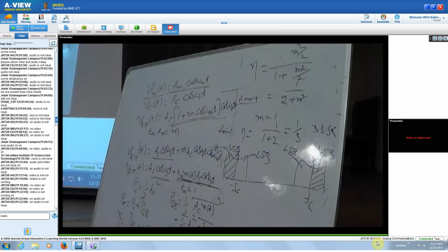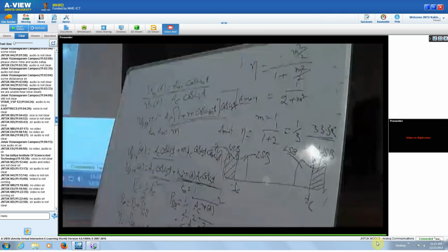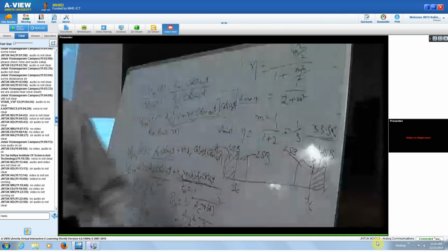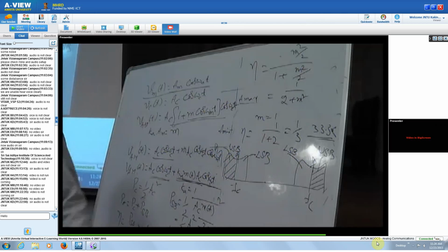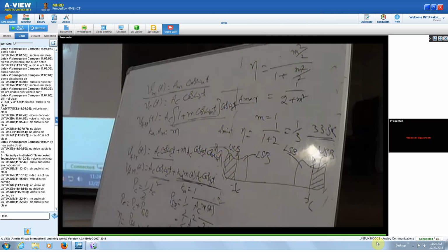That will be the power content in each of the side bands, whereas that 66.7 is our carrier power, which we use only to carry the information and which doesn't contain any information, whereas the entire information is in your two side bands.